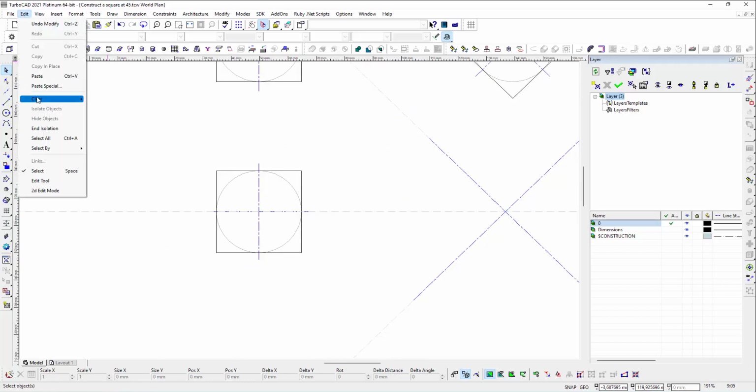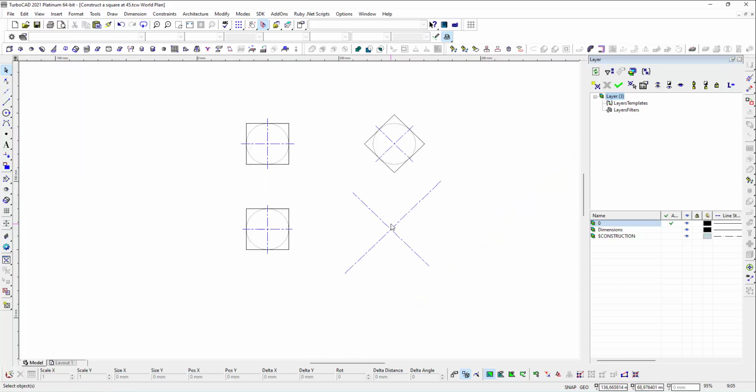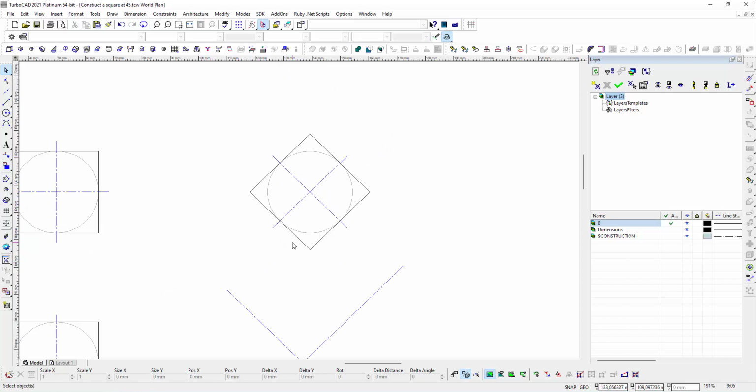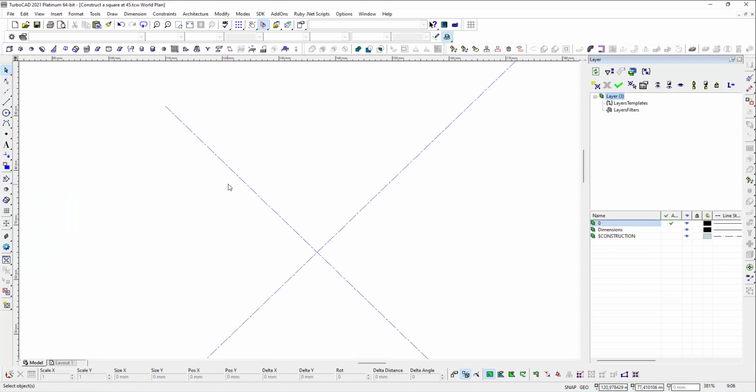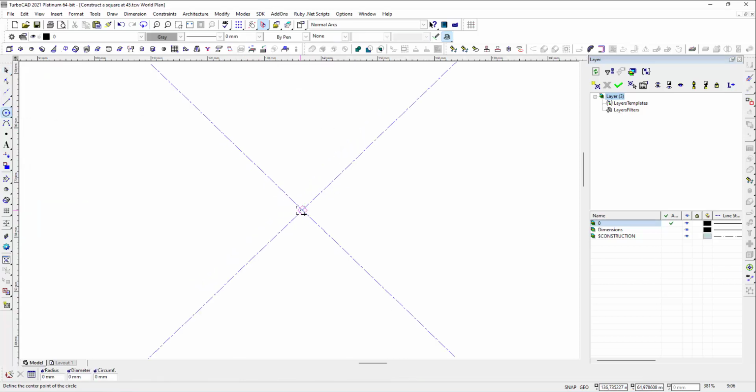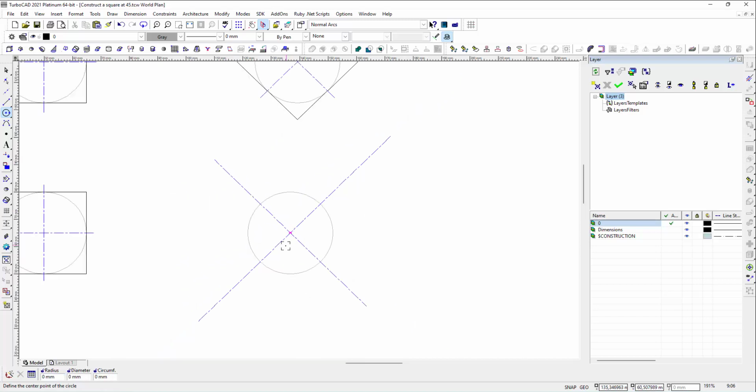Let's just get rid of the water lines. So firstly, we know that the base side of our square is 30 millimeters in length and angled at 45 degrees, so we make sure that our axes are the same. And now we're going to take our compass and, from the center, the shortcut key for selecting the center is I, we're going to go there and say tab 15 for the radius, which gives us a diameter of 30, and there we have the start of it.